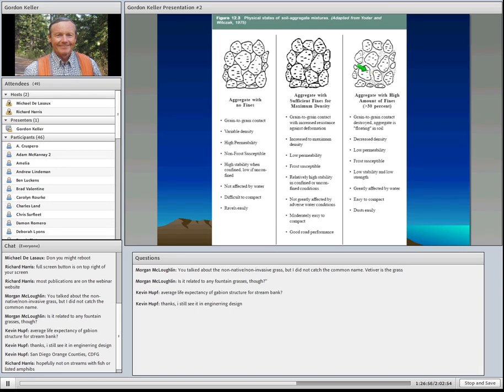And so what you want, and what gradations are based on, is here in the middle. It's aggregate that's got enough fines, say 8 to 15% fines, that it's maximum density, but the rock is still pointing. You still have point-to-point contact here, here, here, of rock to rock, so that's what's giving the strength. But it holds together, particularly on the road surface. So this is what you want for an aggregate gradation: not too much fines, not too little fines, just right in the middle, kind of like what Goldilocks was like.